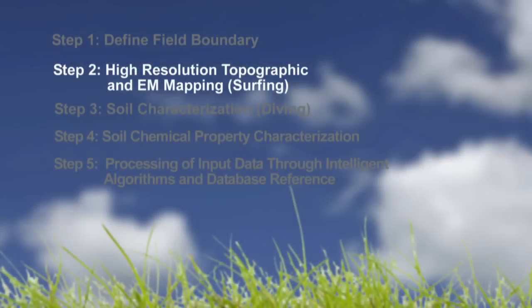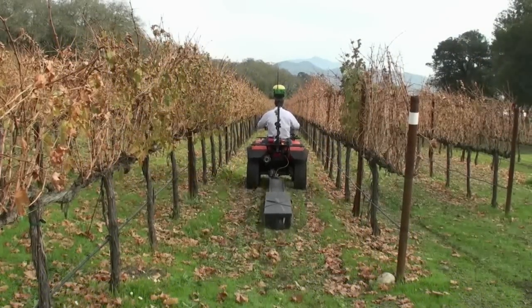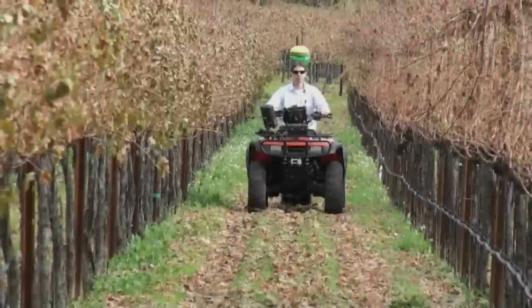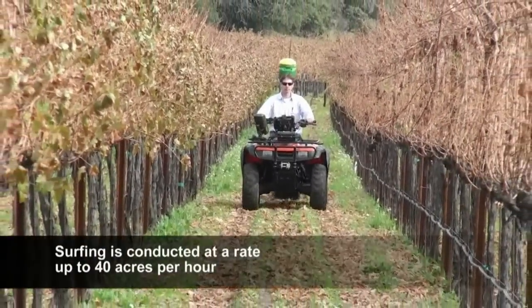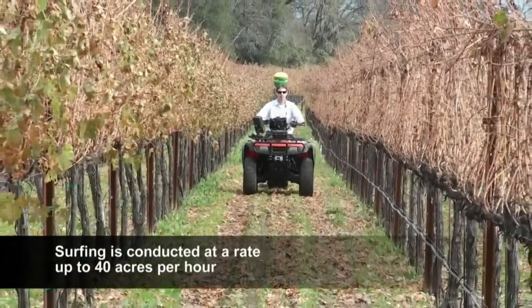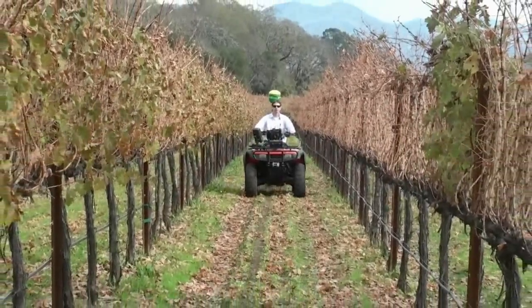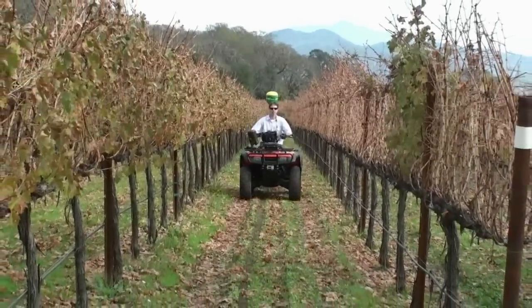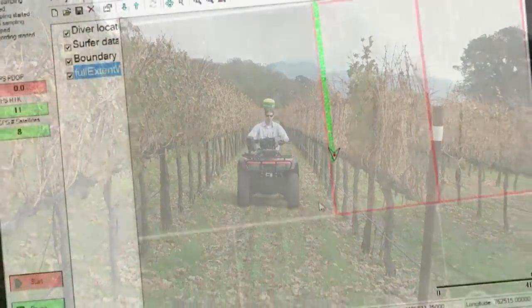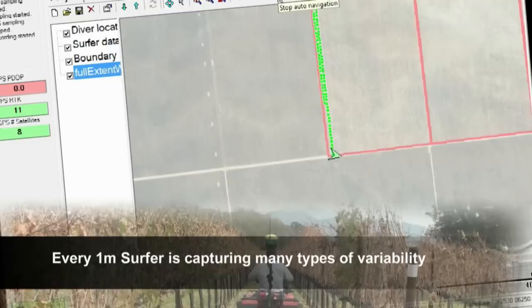The second step, also using the SURFER, fills in the detail within the perimeter defined in Step 1. The system is collecting variability information using the electromagnetic sensor in the sled and its corresponding GPS position. Then SURFER data is collected at a rate of approximately 40 acres per hour. While this is going on, the software is integrating the elevation to create what is called the digital elevation model. Information is being collected approximately every meter.